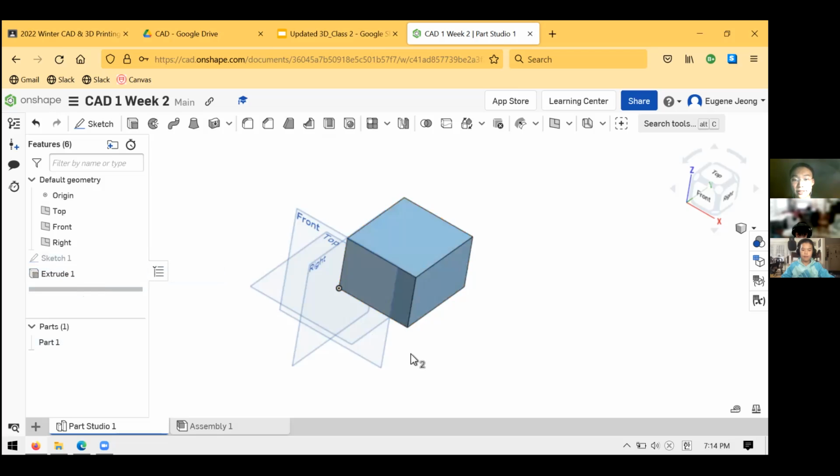that was the rectangle that I drew in the top plane, and I created extrude 1, which was the cube. And what I'll tell you is that as you continue to create things, I could now at this point create another sketch, and I could do another extrude, I could create another sketch after that, and I could work with one of these other tools. Every time I create a feature or a sketch, it'll add itself chronologically, in order of when I did it. It'll add it to this feature tree.